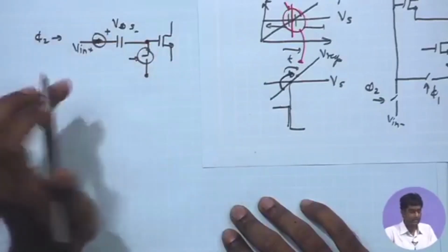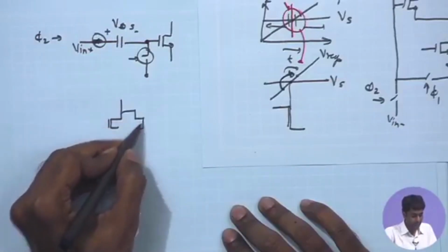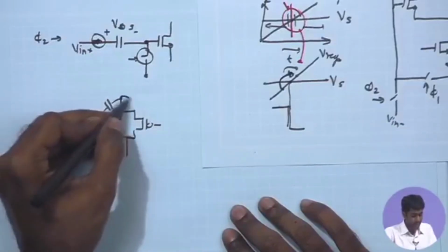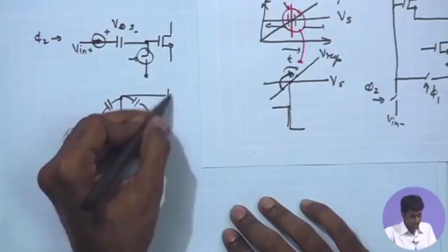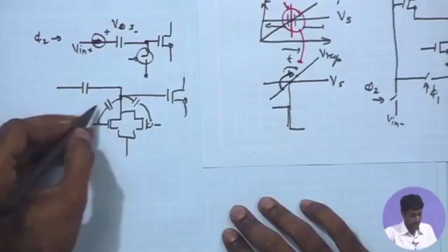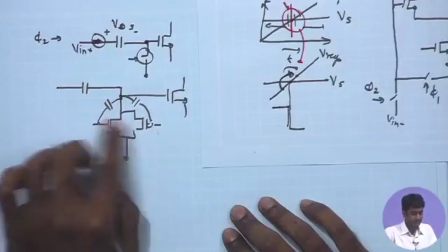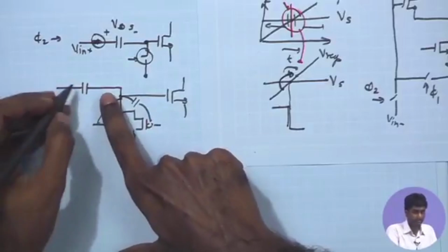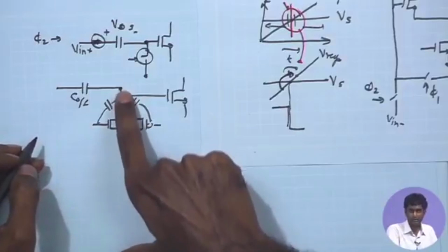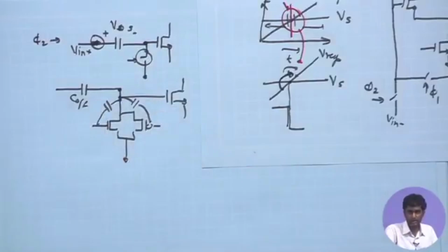And we must make sure that, if I remember the bigger picture, you have these two transistors NMOS and PMOS implementing this switch, and I must make sure that the overall parasitic capacitances contributed by these transistors are much smaller as compared to the C offset, so that the floating node over here does not experience inaccuracy, does not increase or decrease this voltage because of the dumped charges arising from clock feed through and charge injection from these switches.